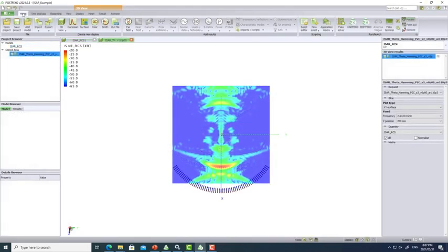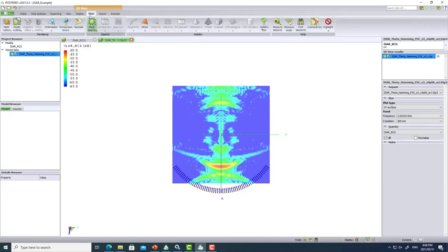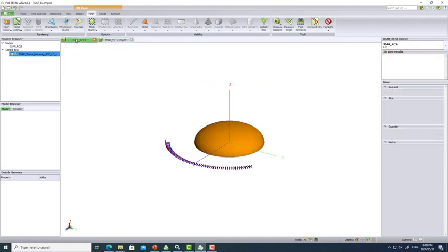The calculated inverse synthetic aperture radar image for the chosen processing and angular range, shown here on a decibel scale in a three-dimensional view, appears to be more complex than we may have anticipated. If we overlay the target with this ISAR image and take a closer look at it, we can see that the radar processing highlights details of the object that we were not aware of. This simple and friendly target is in fact composed of different materials, giving it a unique and identifiable radar signature.